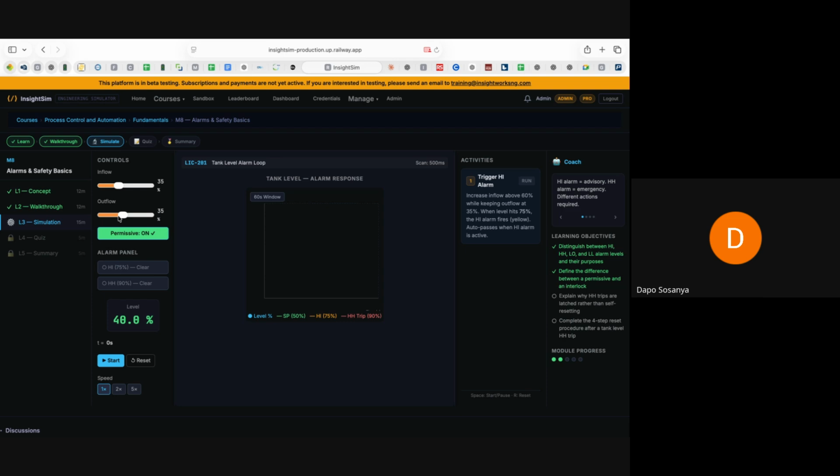So you can begin to see how instrumentation quickly escalates. The inflow into the tank, there is a pipeline there. There is some monitoring and control you want to implement on the pipeline, not just on the valve. You can implement flow, right? You want to know the flow rate, the rate of flow into the tank. So you can implement that. On the outlet also, you can implement flow. Are you following? Yes, sir.